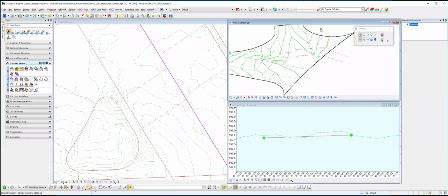the second you move the boundary, the model moves with it. Occasionally you'll notice that you're moving the boundary and the model isn't moving, and that's the two have gotten somewhat disconnected in the program. So you'll have to just select your boundary, remove it from the terrain model, and then just put it back, and it'll automatically then hook back up again.